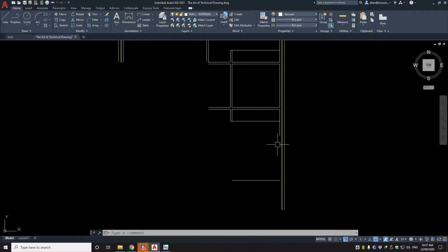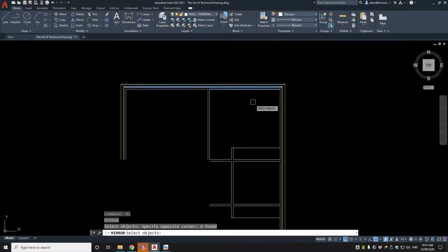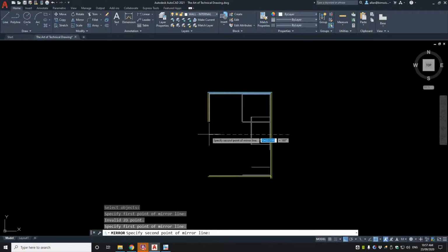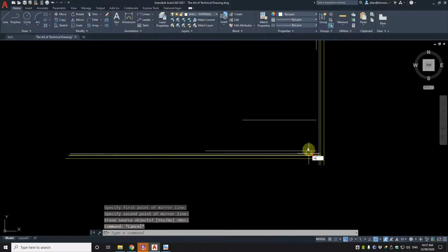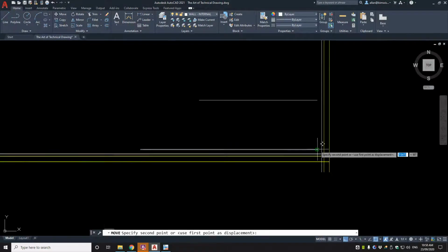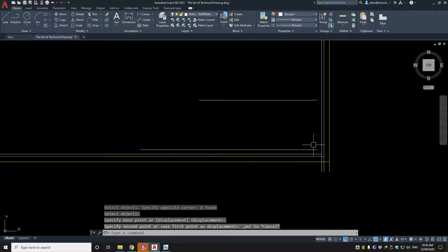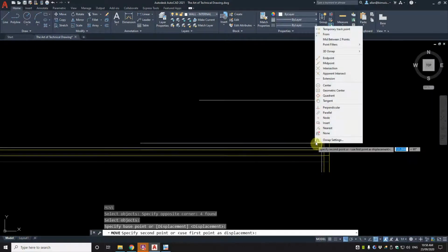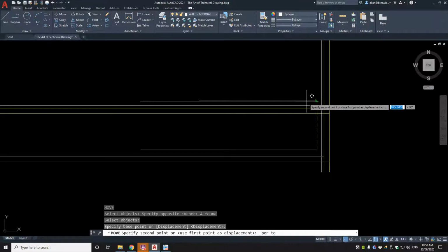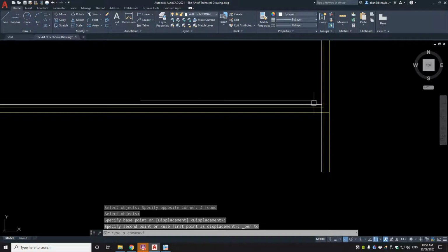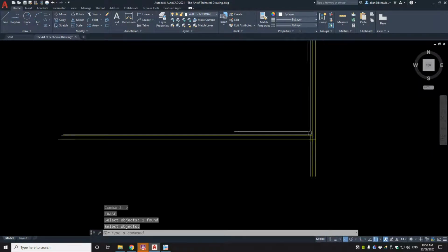So I'm going to draw the balance of the bedroom there now. Now here what I could do too is also mirror these walls over. Now I know that's where my bedroom has to be, so I've mirrored that over. Now I'm going to move those three objects from that endpoint and move those three objects from that endpoint, and then I'm going to go shift right click and perpendicular, so I want it to go directly onto that line, and that is bang on now. So I can delete that line, so I don't need that extra one.